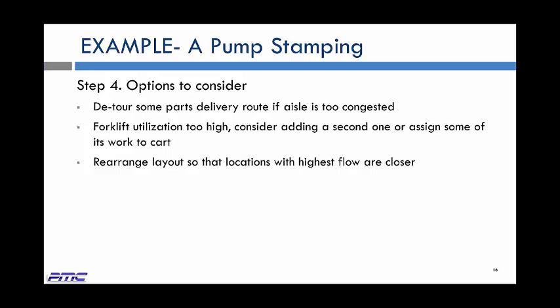If you move this department from location X to location Y, and this is the cost, can the cost be offset by reducing the number of forklifts required? So you need to do a cost-benefit analysis to see whether that kind of move is going to help in reducing your total travel time, or reducing the number of manpower required.